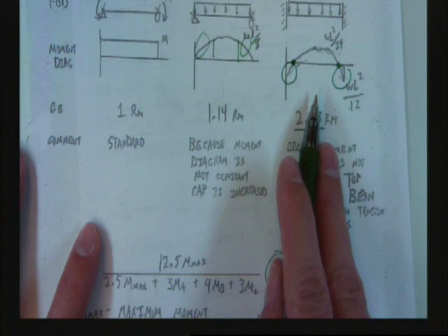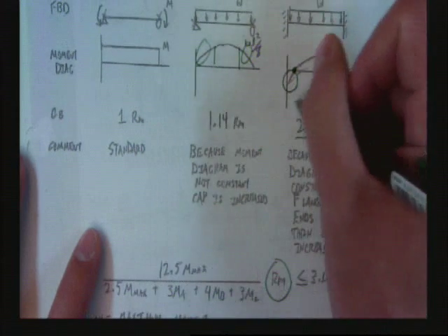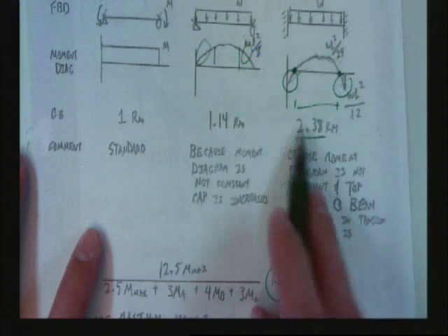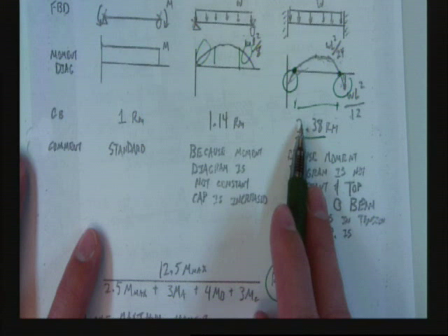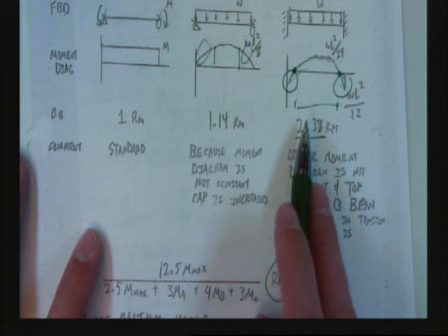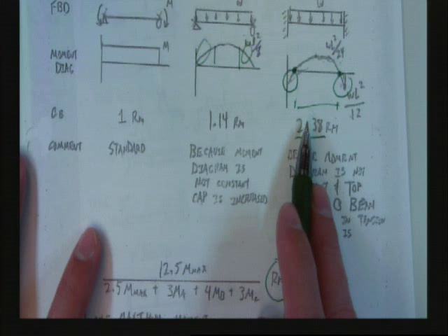There are people that will say, oh, I'm going to use this as my L sub B because that's my area that's actually in compression. They'll say, oh, I'll use a C sub B of 1 just to be conservative. That's wrong. If you luck out and your building doesn't collapse under the loading, it's because you just got lucky.